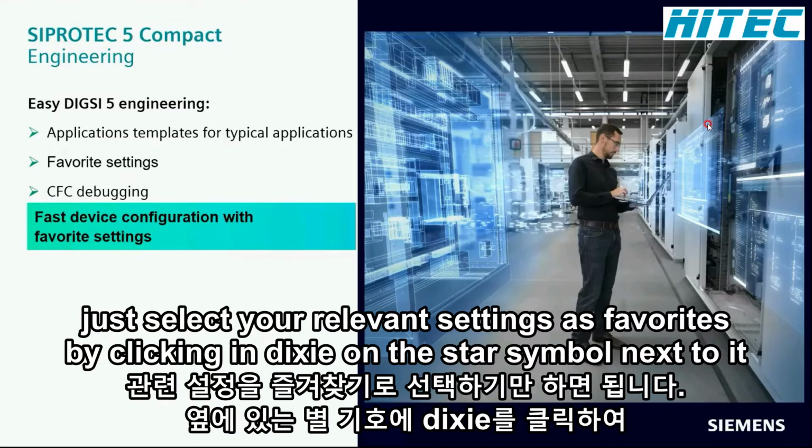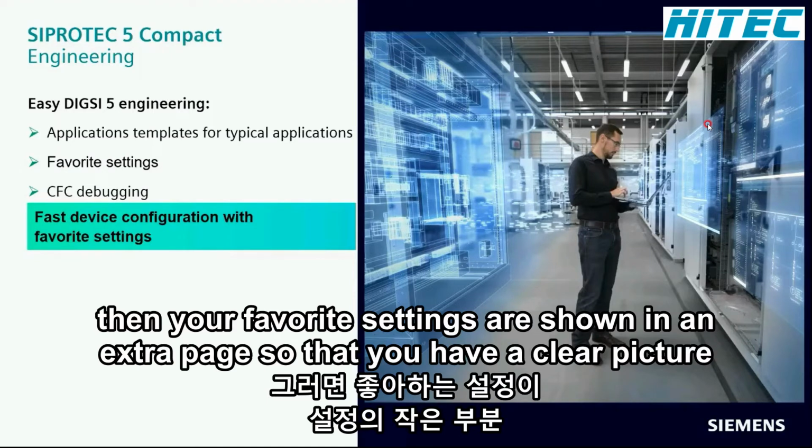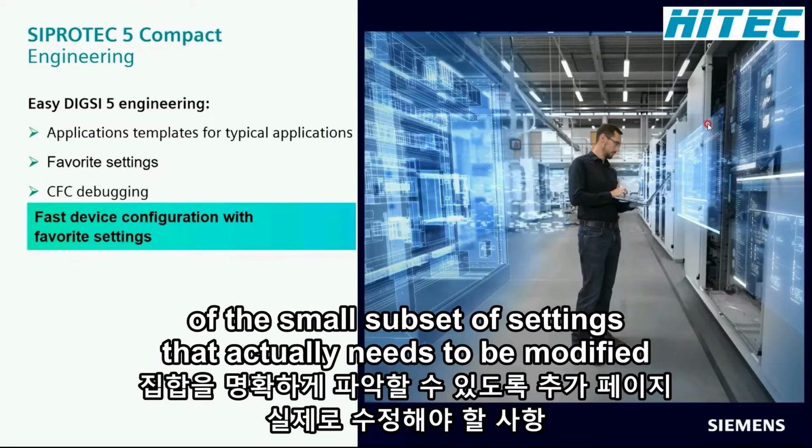Just select your relevant settings as favorites by clicking in DIGSI on the star symbol next to it. Then your favorite settings are shown on an extra page so that you have a clear picture of the small subset of settings that actually needs to be modified.